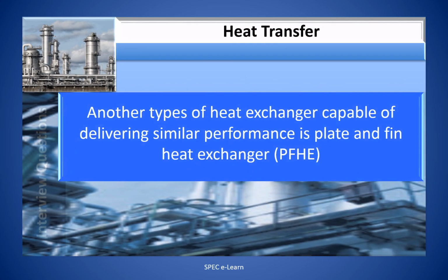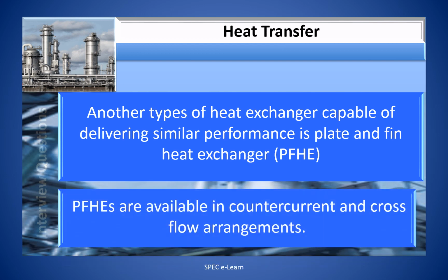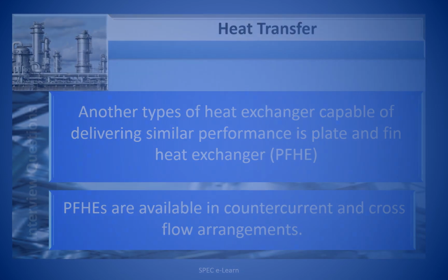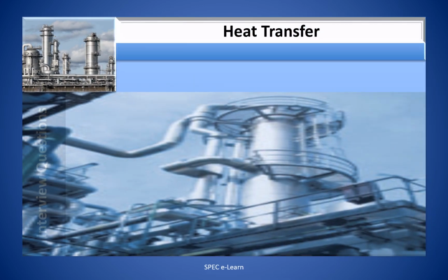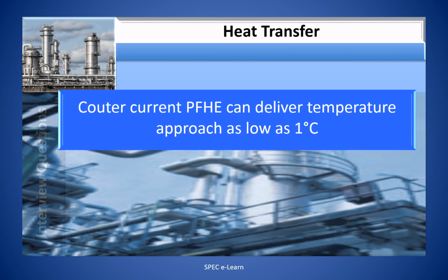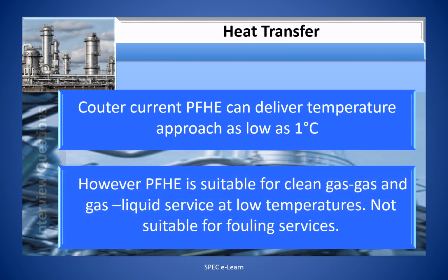Another type of heat exchanger capable of delivering similar performance is plate and fin heat exchangers. PFHEs are available in countercurrent and crossflow arrangements. Countercurrent PFHE can deliver temperature approach as low as 1 degree centigrade. However, PFHE is suitable for clean gas-to-gas and gas-liquid service at low temperatures, not suitable for fouling services.